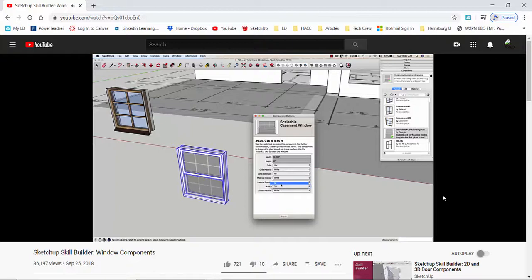So right now I have a screen on here. If I say no, I don't want that screen, and hit apply, the screen goes away. Grill, nope, let's get rid of that grill too. Apply that, boom, that's gone. This is pretty cool. So you can actually see ones like this that will redefine, is it single hung, double hung, fixed, whatever it is will actually change on the fly as you change these properties.